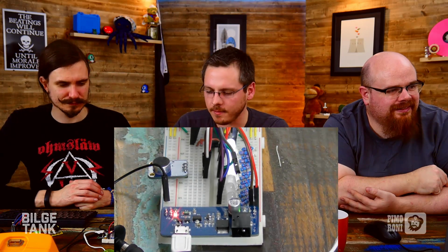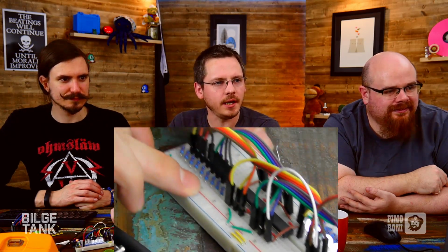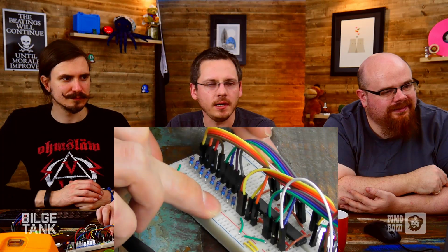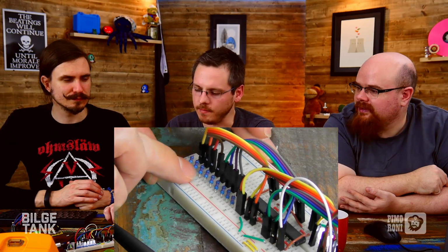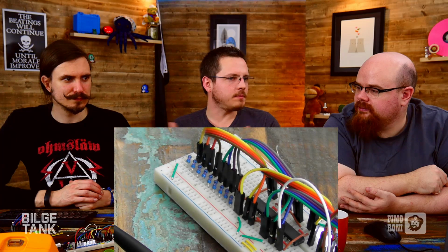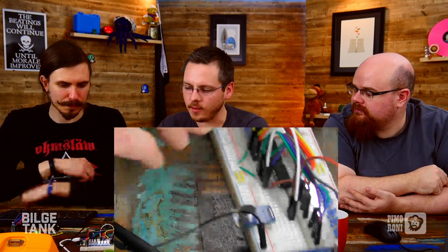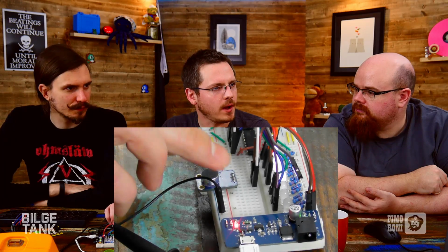Yeah, basically. And again, like Phil was saying, the thing about this being linear resistors here means that we've got a linear ADC. There's no need for that to be linear. You could make this logarithmic, and it depends on your purpose really. Quite interestingly, with the audio one, you can tell there's some sort of baseline noise it's picking up, roughly halfway, and only by tapping it do we actually peak. But if we tweak those resistor values, we can make it much more sensitive to certain areas.